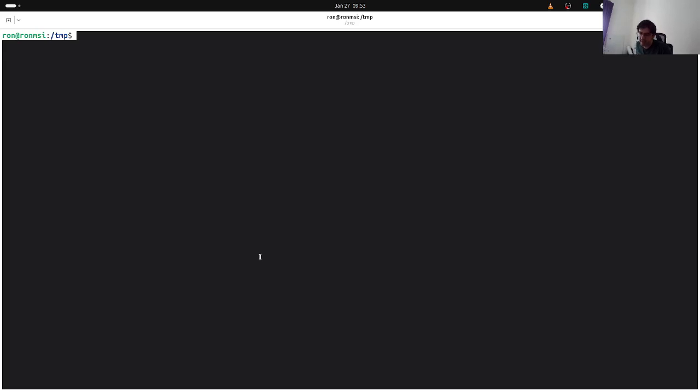And once we have this, we are able to put our own software, our own Linux on an SD card, and from this point we can move on and work with the distros that we are manufacturing. But very important, a lot of modding instructions don't go over replacing the bootloader. They expect to use the mechanisms of the existing bootloader. So they will look for a boot script on the first FAT partition of an SD card, and then do all kinds of things. So we do not do that.